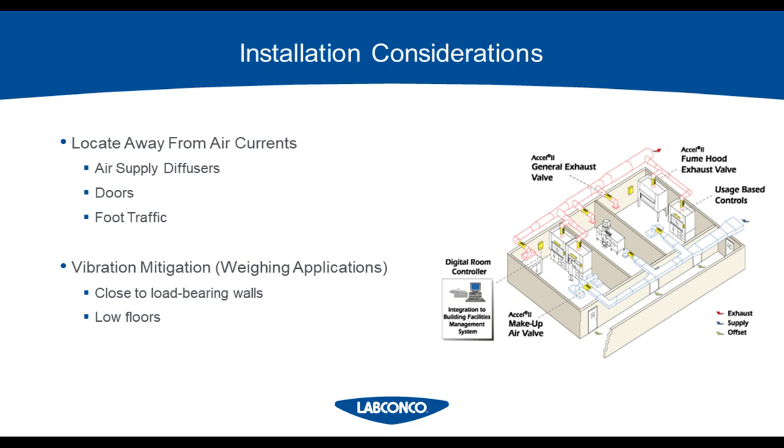Might feel good in the summer, but it also may ruin the containment characteristics of a hood. Also, if you have a very sensitive balance that's helping weigh nanomaterials, you definitely want to stay close to a load-bearing wall, and if you can, be located on a lower floor, or use items such as a marble table or dense materials that can help eliminate building vibration.